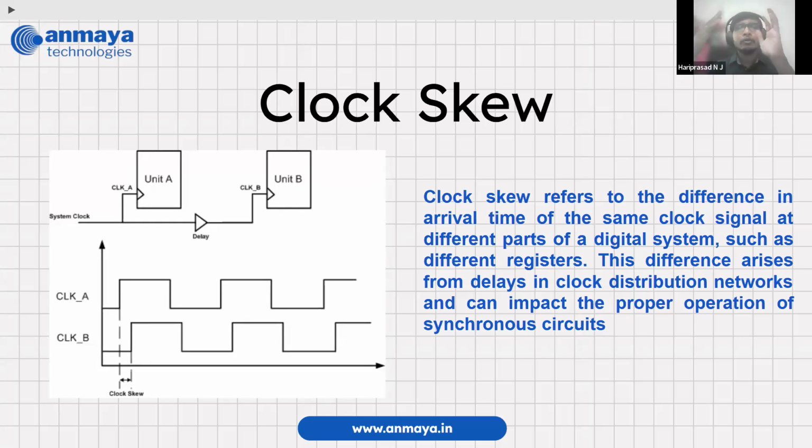That will cause a lot of skew and critical path issues, and also don't use that data path clock as your actual clock. When the design is congested, your clock path also will have some issues. Usually that will be a low latency path inside the FPGA, but these clock skews occur especially when your clock is coming from external devices.